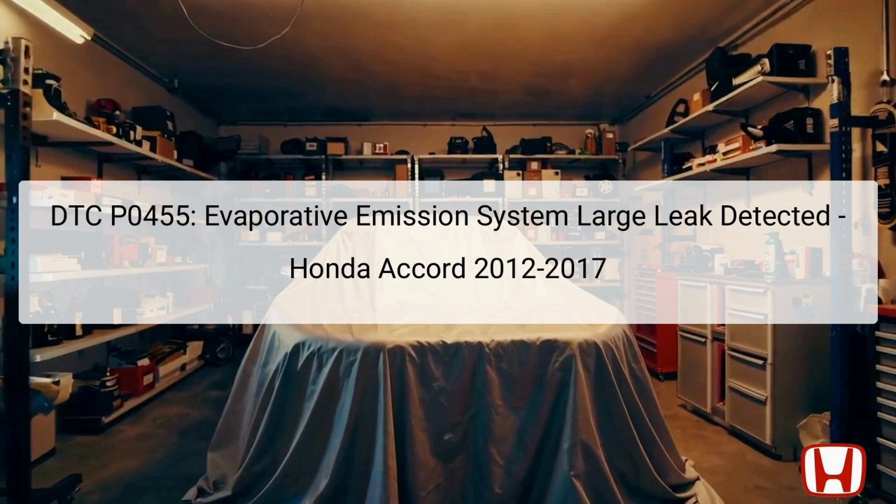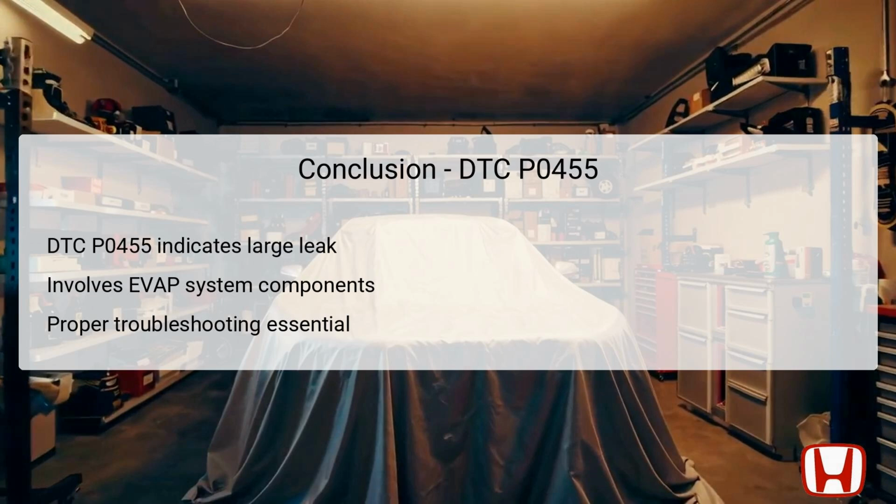It differentiates between acceptable leak sizes as small as 0.02 inches and larger leaks up to 0.09 inches. When the PCM, Powertrain Control Module, detects a leak above the normal range, it triggers the P0455 code, requiring further investigation and diagnostic procedures to locate the leak and rectify the issue. In summary, DTC P0455 points to a large leak within the EVAP system of the Honda Accord from 2012 to 2017 and requires careful analysis and troubleshooting to resolve effectively.